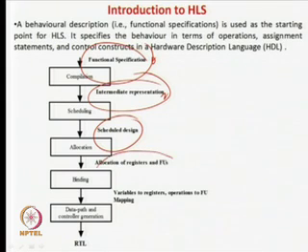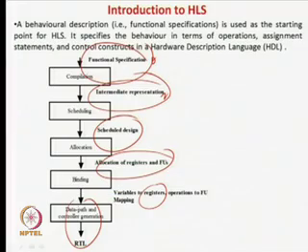Then whenever we have scheduled all the operations, we allocate some hardware units for this. In some cases we may require hardware adders, or in some cases we require a multiplier and so forth. And finally, the variables will be allocated to registers, then there will be multiplexers and so forth. So, first we go for scheduling, then we allocate it to the hardware, and then we bind the operations to the hardware, like say addition 1, addition 2 will be done by adder 1, addition 4 and 5 will be done by adder 3 and so forth. And finally we go for control and data path generation, where we will see what we mean by control and data path, and finally we get the RTL design, or your block level architecture design.